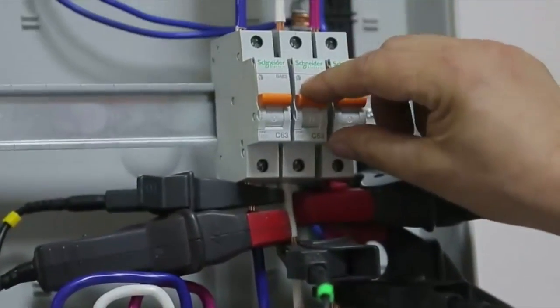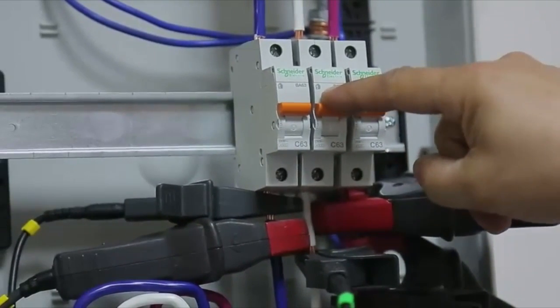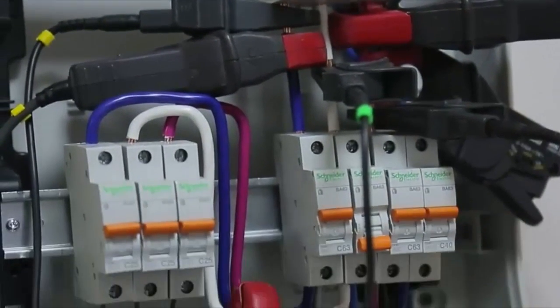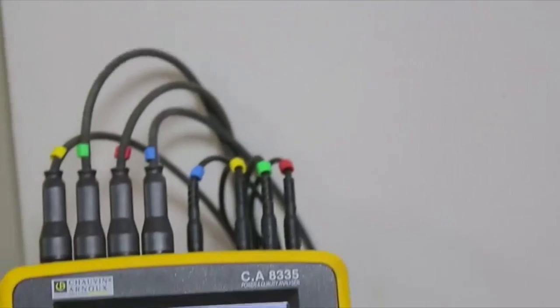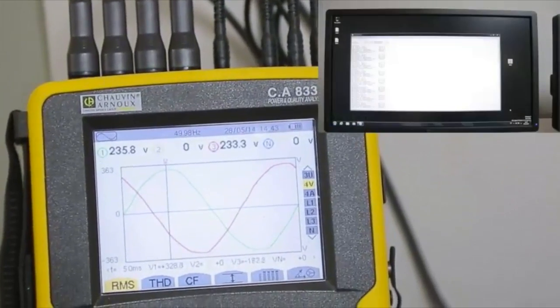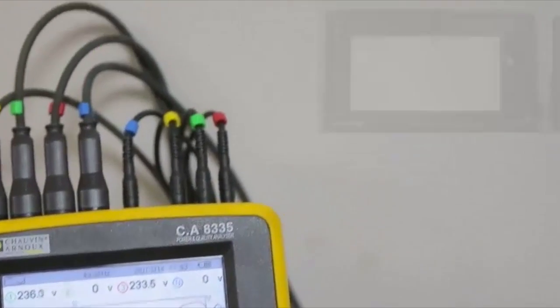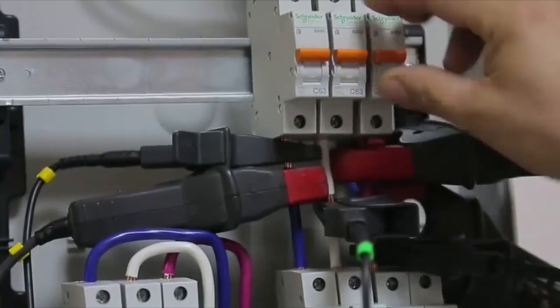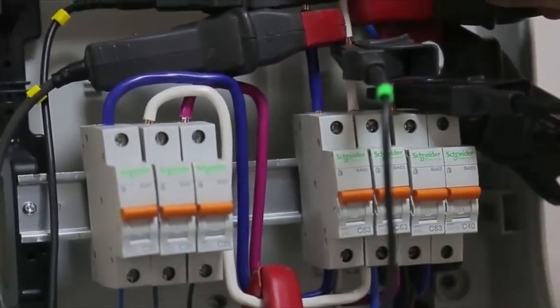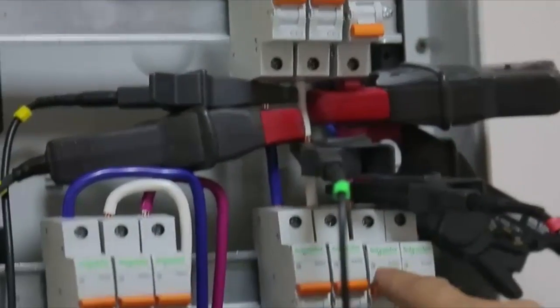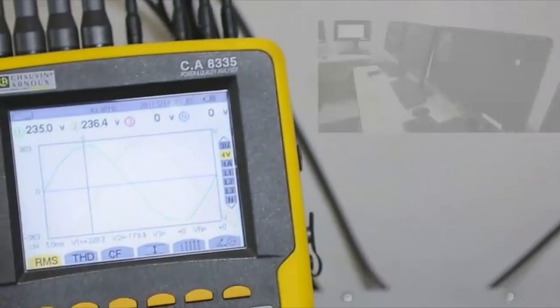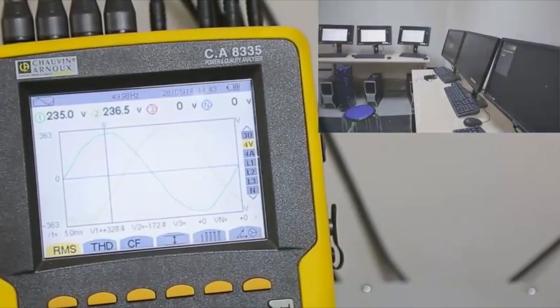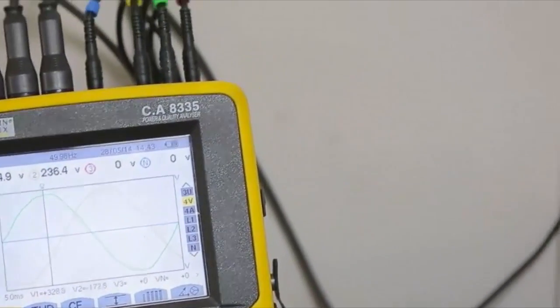Now, disconnect phase B by two single-phase automatic circuit breakers. Phase B is disconnected but servers continue running. Reconnect phase B. Disconnect phase C. Observing no phase, but operation of servers is stable. Restore original condition of the three-phase system.